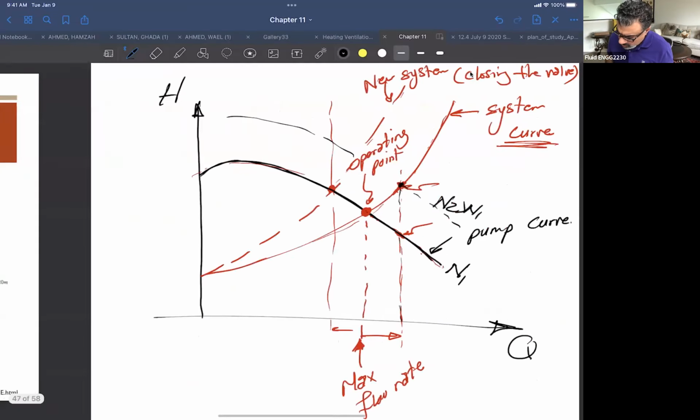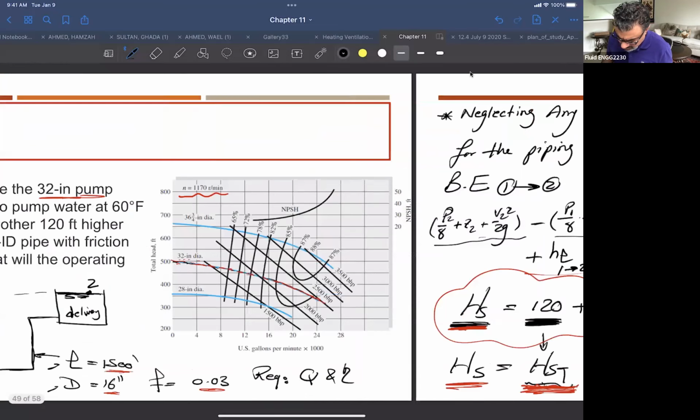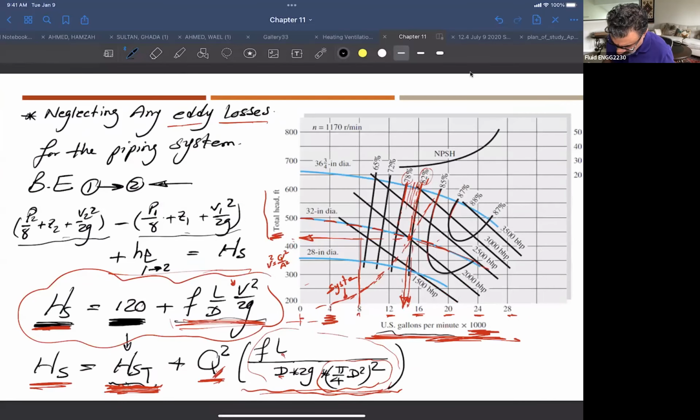Okay. When we solved this problem last time and we talked about the Bernoulli equation here, we didn't mean that you really apply the Bernoulli equation between point 1 and point 2, because the pump is not there, right? You don't see a pump here, right? You don't see an H pump here, right? But it's just giving you the same idea. This is the difference between the two energies, if we consider velocity and also the pressure.